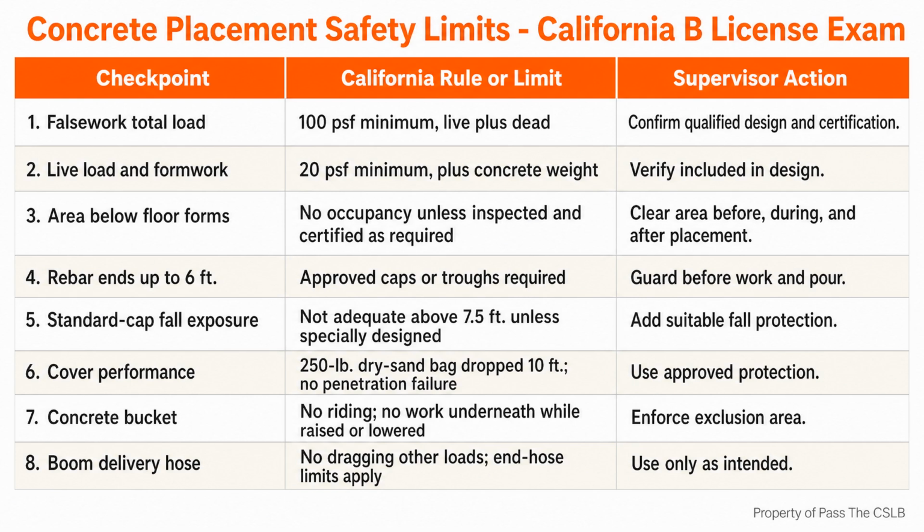Placement quality and placement safety meet at sequencing. The testing team needs access to sample the concrete. The crew needs a workable path that does not force unsafe hose handling. The formwork and shoring need approval before load is applied. The reinforcing steel protection needs to match the fall exposure. The truck sequence needs to support continuous placement without pressuring anyone into an unapproved mix change.